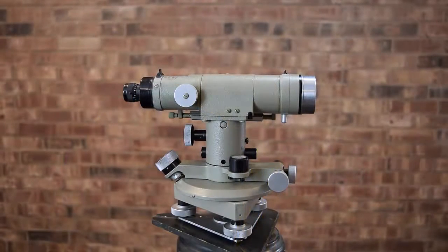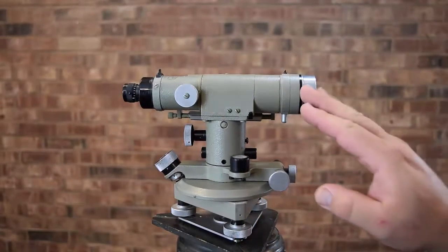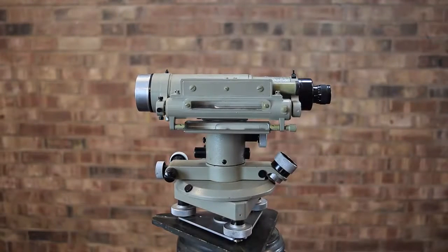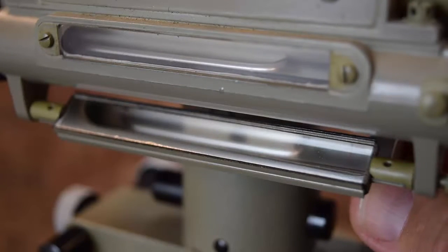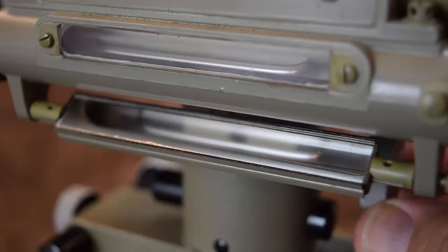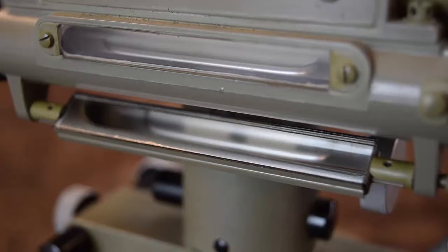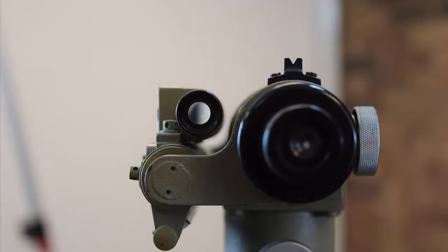The tilting level represented the next generation of leveling precision. This one was manufactured in the 1940s. As optical science had improved, it sported a shorter telescope and it had an innovative feature that allowed more precise leveling: the split bubble. Below the long bubble tube, an adjustable mirror reflects light into the fluid and bubble in the cylindrical tube. Using a separate eyepiece and another internal mirror, the operator views two halves of the bubble image and adjusts the level carefully to align the two images.